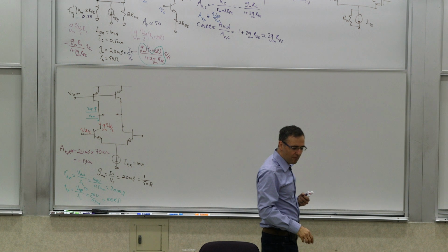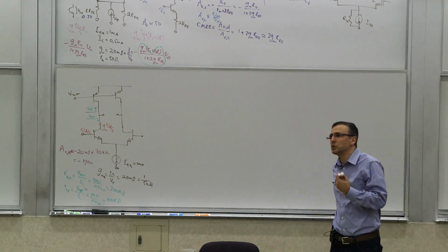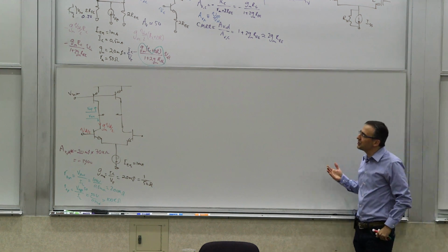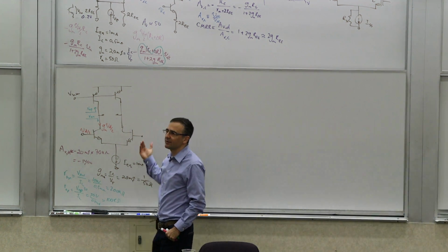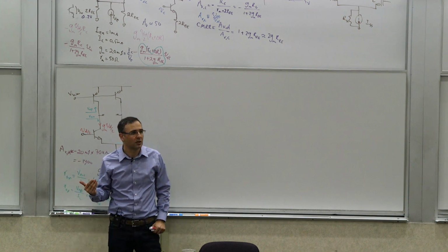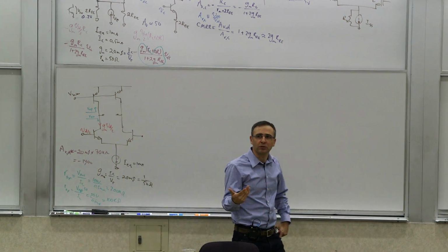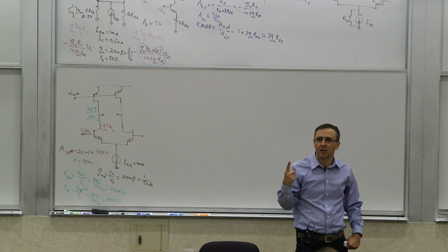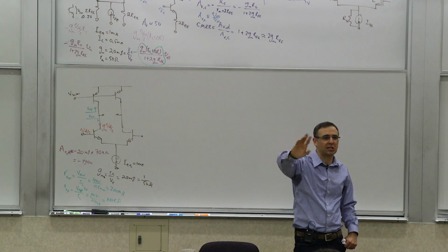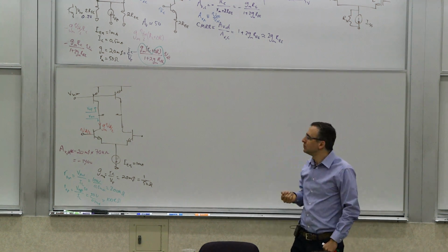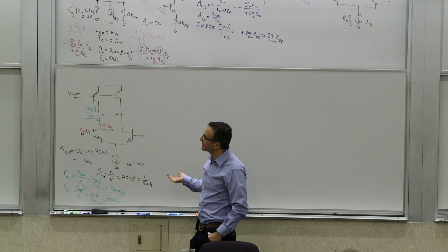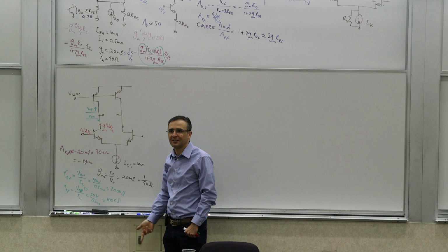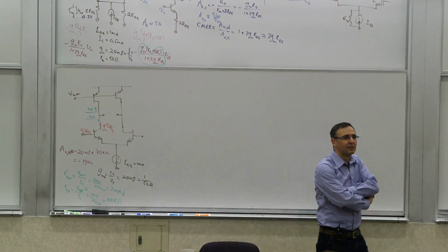Now, the other question is, some of the things we do are targeting something like an op-amp. So a lot of times, what you actually want to do is to get the output not differentially, but single-ended. So what if you wanted to make a single-ended output? You don't need two outputs, you just have one. Let's say something that goes to the next stage that has a single-ended input. If I need a single-ended output, the easiest thing to do is to take it from one of these nodes, right? And just discard the other one. What happens if I do that?